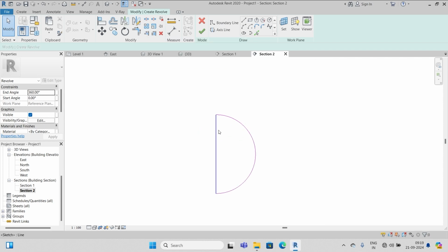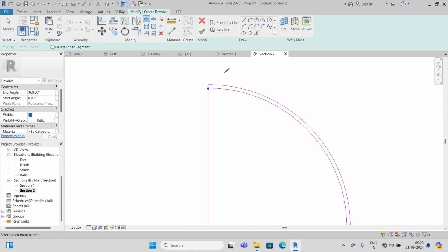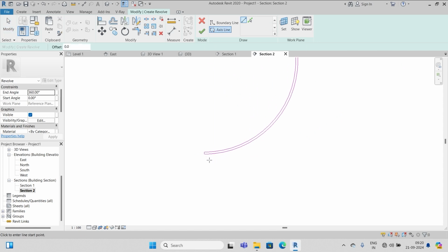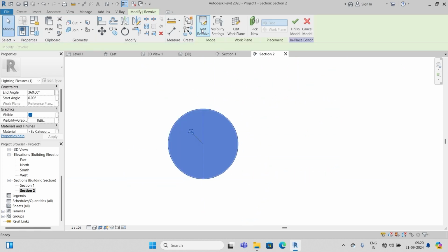Using the trim extend single element tool, I slice the half, then I offset it 1 mm. Then take the split element tool and then cut the line at 2 points. Here, here, then this axis line, here to here.